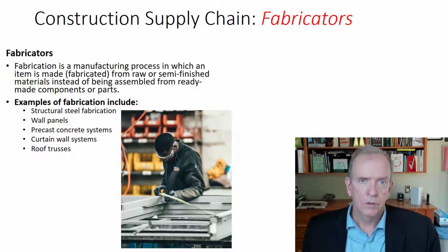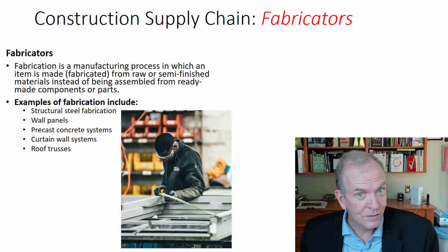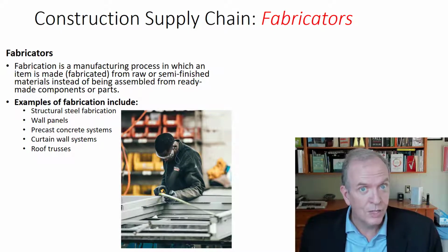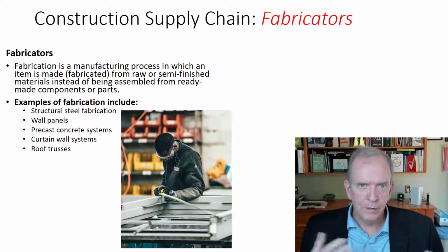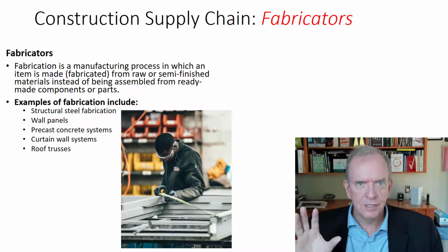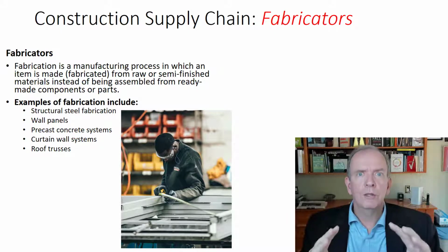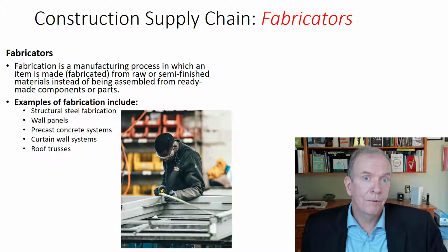Now, always there's pluses and minuses. Traditionally in construction, the problem with prefabricating too many things is that maybe it doesn't fit when it arrives. Maybe something on site's not quite the way it should be. The advantages of BIM, building information modeling, we're able to do a lot of 3D planning, and we can look for interferences. Like we do this fancy duct system, and all of a sudden when we're on site we see a pipe running through right where we want to put the ducts, and we prefabricated the duct. That's going to be a problem.